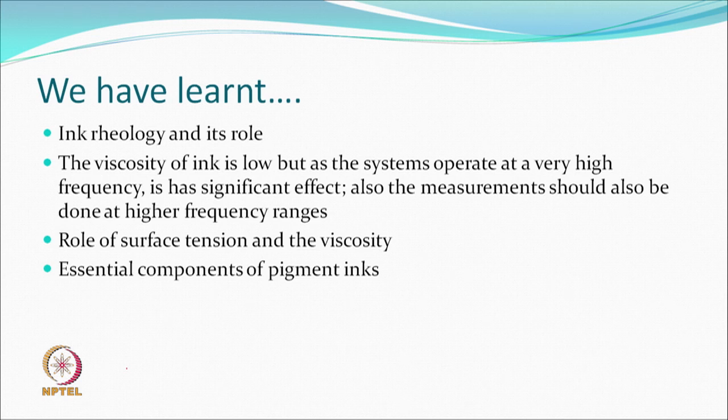So, today what have we learnt? We have learnt that ink rheology has a role to play. The viscosity of the ink is low, but as the systems operate at a very high frequency, it has significant effects. The shear rates can be very high around the nozzle.